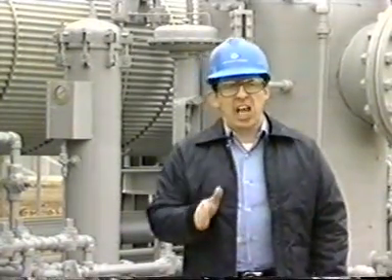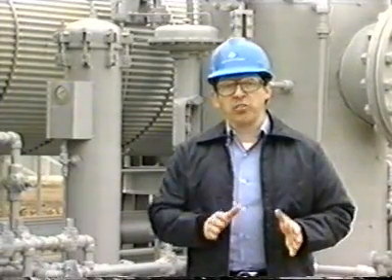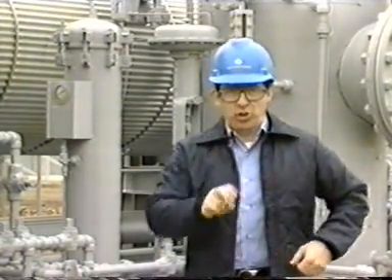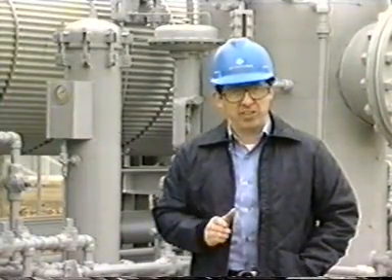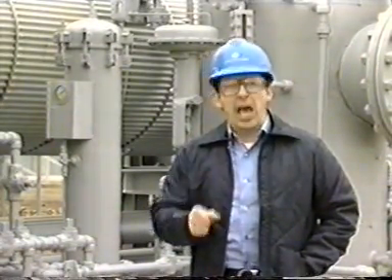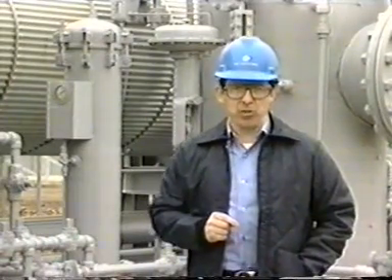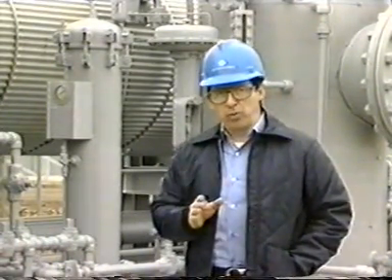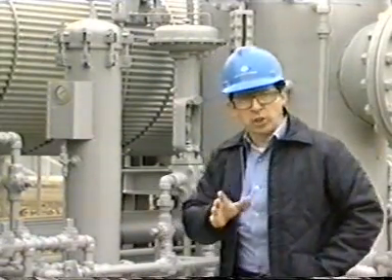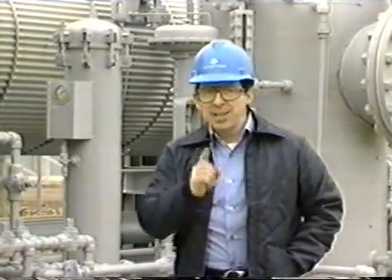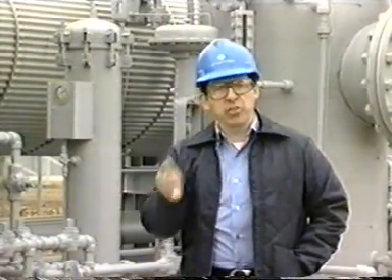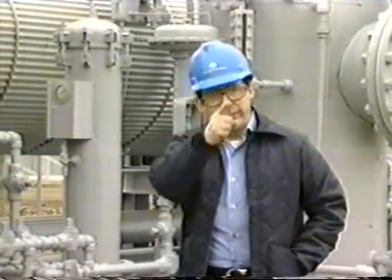Filters are installed in the glycol stream to remove solids and other contaminants which may cause plugging and foaming. There are two types of filters commonly used in gas dehydration systems. One type is used for solids removal, and the other for dissolved contaminants removal. For solids removal, fine screens, sock type, or cartridge filters are used. Now, solid particles cause erosion of pump pistons, valve seals, and discs, plugging of equipment, and foaming.